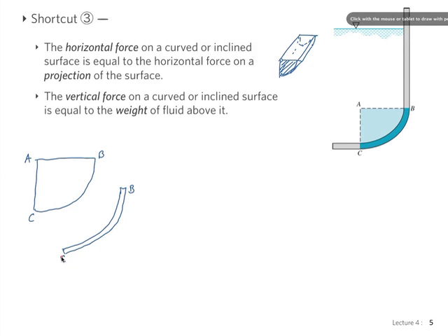And the forces: we have a vertical force here, FAB. We have a horizontal force here, FAC. We have the resultant acting here, and on the wall equal and opposite. Basically, this is what we're looking for, equal and opposite here, F. So I've separated the wall from the volume of fluid to obtain F.